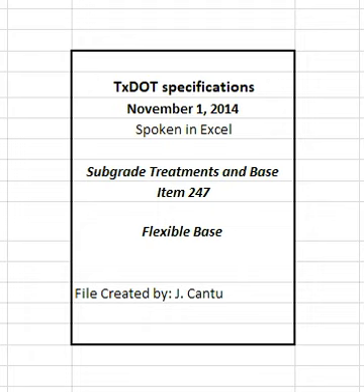6.2 Flexible base, roadway delivery. Payment will be made for the type and grade specified. For cubic yard measurement, in vehicle, in stockpile, or in final position will be specified. The unit price bid will not include processing at the roadway.